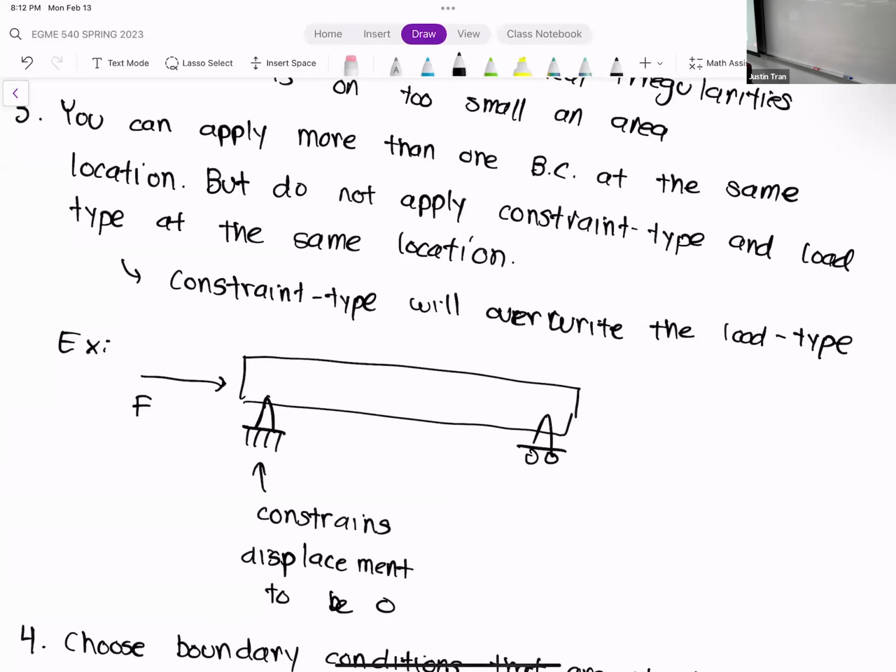Then what you do from there is run multiple simulations, maybe hundreds or thousands of simulations, each with a random assortment of conditions. Once you run them all, you take the statistics for the results, so you get a mean and the standard deviation for the results.